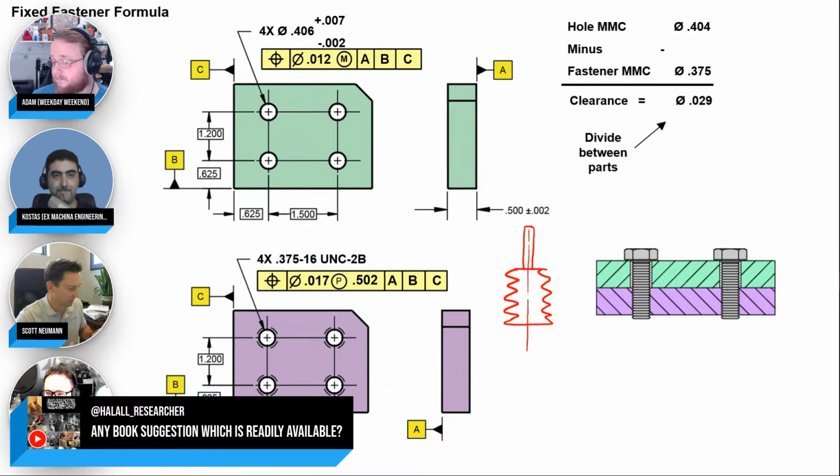Think about that for projected tolerance zone too. You're threading that thing in there, and then what's sticking out is your awesome little ground diameter on the pitch, so you can measure that. Now, the only thing with those is they can be a little sloppy, right? They can kind of rattle around in there a little bit. So some of them have slits put into them, and then the slits are constantly trying to expand it in there. So when you put it in there, that expands, because it's got the slit in it. And so then it takes out the slop, and now you're pretty much centered up on the pitch. Like, that's the axis that you care about.